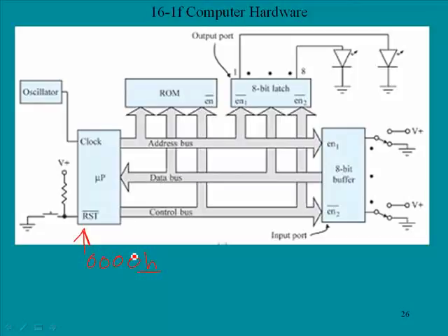First, the microprocessor needs an instruction. So it outputs the program counter, which is currently set to this number right here, program counter, which is internal to the processor, to the address bus. So this address goes out on the address bus. It also activates a control bus signal called memory read, okay, and that is right here, control bus memory read, and that would be going over here.